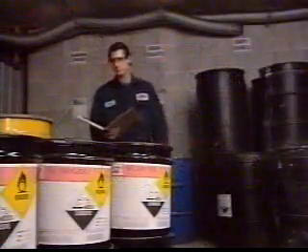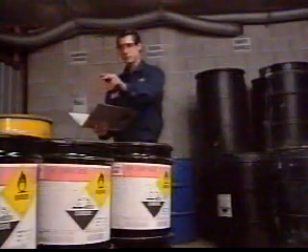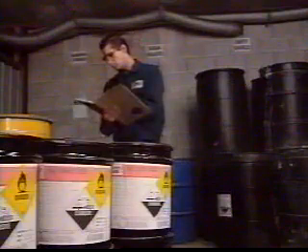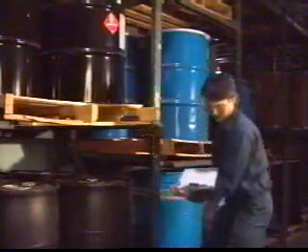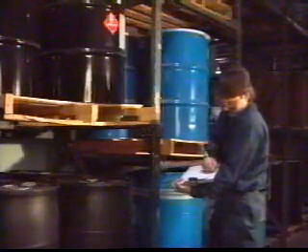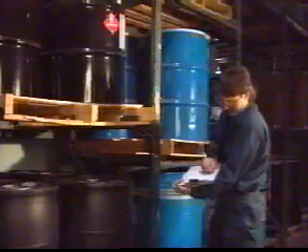An important step in learning about hazardous chemicals is knowing what chemicals are used or stored within the company. This includes chemicals taken off-site for use in other locations and those stored away from the main plant. Compiling a hazardous chemical inventory sounds like an easy job, but all too often the list is not complete. For instance, the inventory could be missing hazardous chemicals that someone thought were harmless. However, if a container label shows a hazard warning, the chemical must be on the inventory.